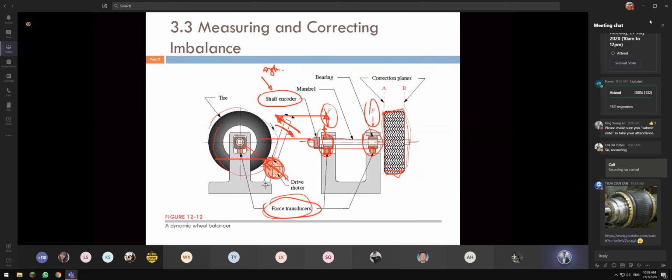So in future, when you go to a tire workshop and they do balancing, you can stand at the side. You will listen to the sound initially, then when they press the start button, you will hear an acceleration sound where the motor is spinning up the wheel, and then suddenly there will be a sound like the drive is detached from the system. Actually, by that time only the measurement starts. Okay.